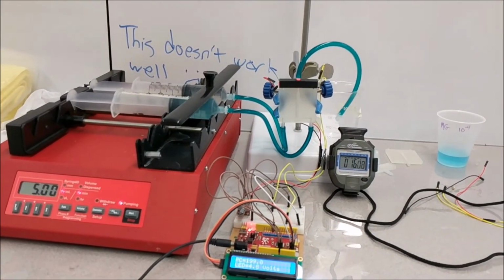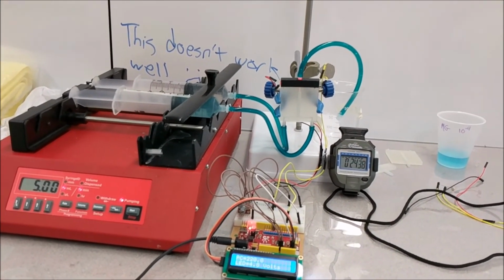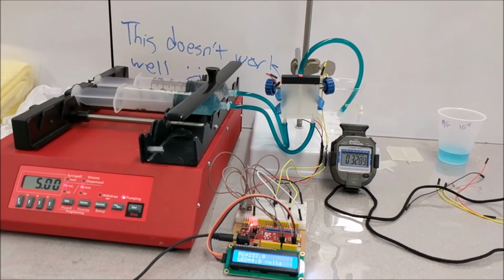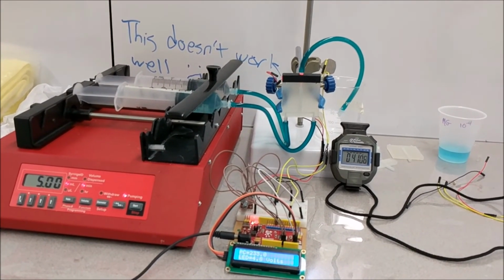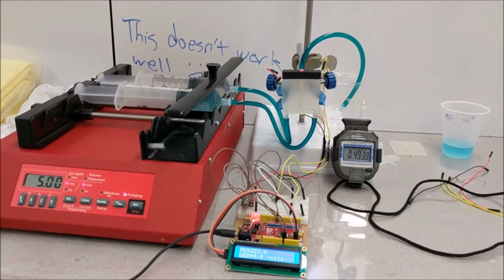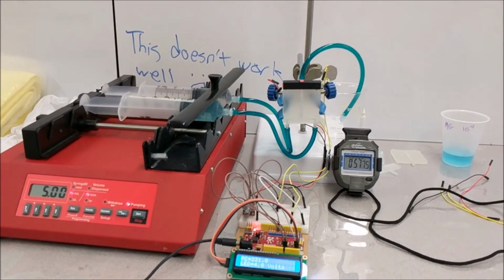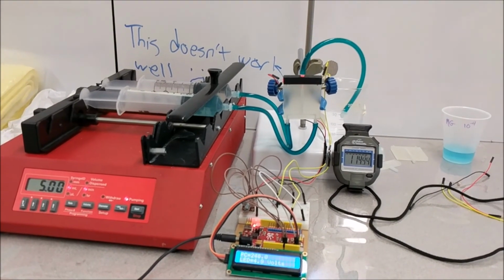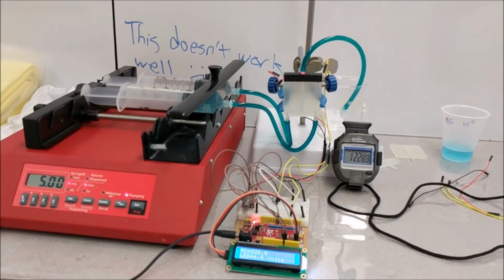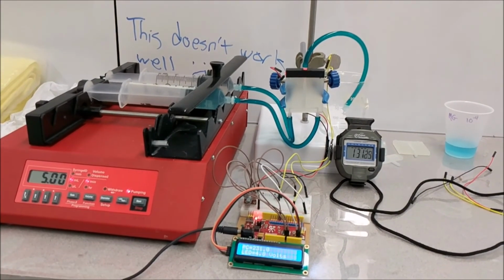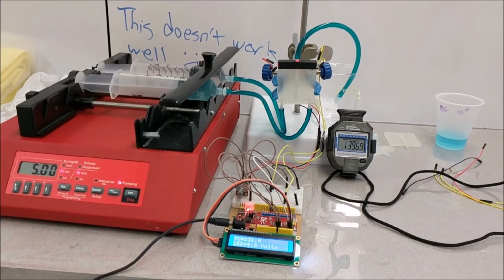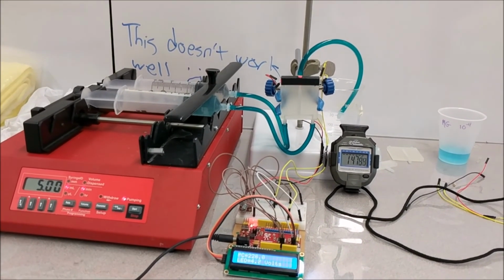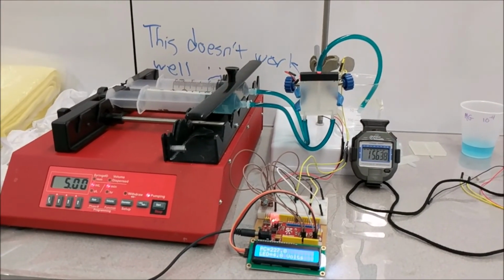30 milliliters of 1 × 10⁻⁴ molar malachite green was placed in one syringe, and 30 milliliters of 0.5 molar sodium hydroxide was placed in another. Both syringes were hooked up to the reactor and secured in the syringe pump. A specific flow rate was set, and a photometer reading was taken every 20 seconds once the components were flowing completely through the reactor. Trials were run with flow rates of 5 milliliters per minute, 10 milliliters per minute, and